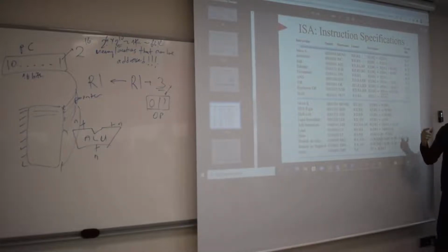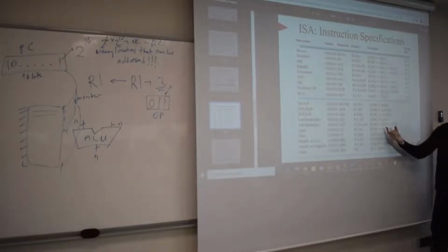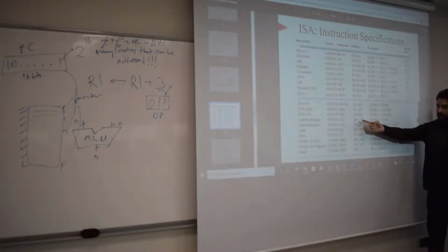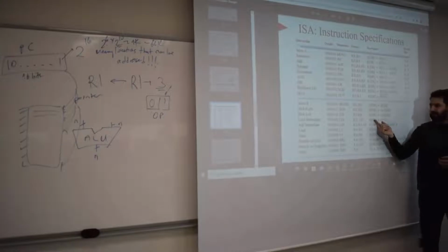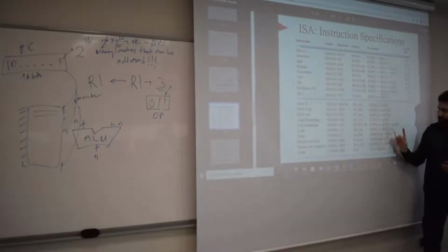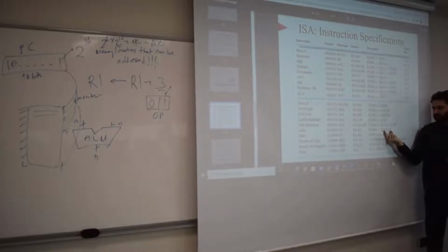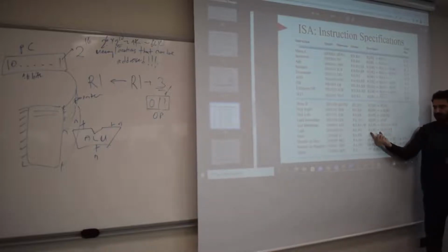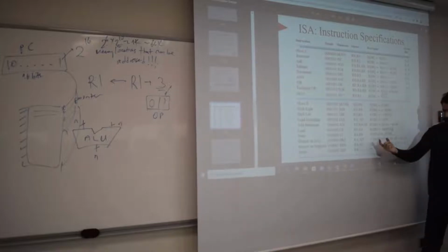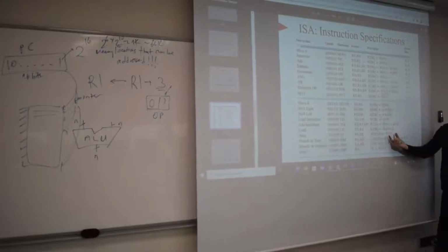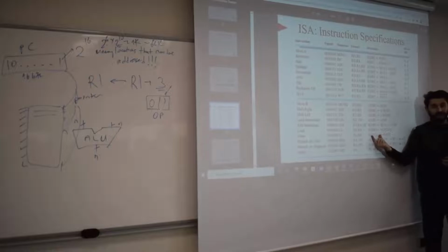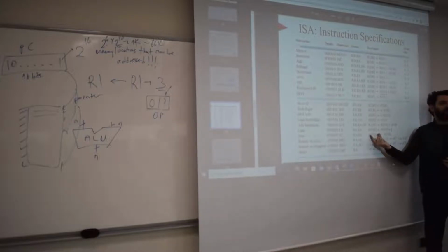And there we also talked about address calculation, right? Because here you see load immediate, this is immediate type, by the way. I'm sorry about that. We got the load instruction here. You see the content of a register becomes the memory address, right? And then we write to the register. And we got the store operation. The contents of a register is written to memory, where the content of another register becomes the address of the memory that we write this content to.